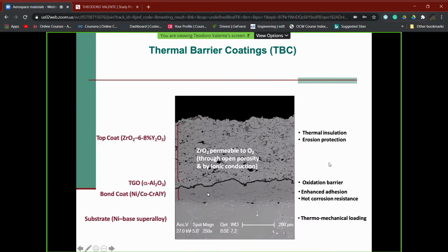be formed during service. And if we put our attention on yttrium oxide, we have it in the formulation of the top coat, and so we can expect that the bond coat can show during service a thermal expansion coefficient which is intermediate between the value of the top coat and the value of the substrate, the superalloy. Thus explaining both functions of the bond coat.